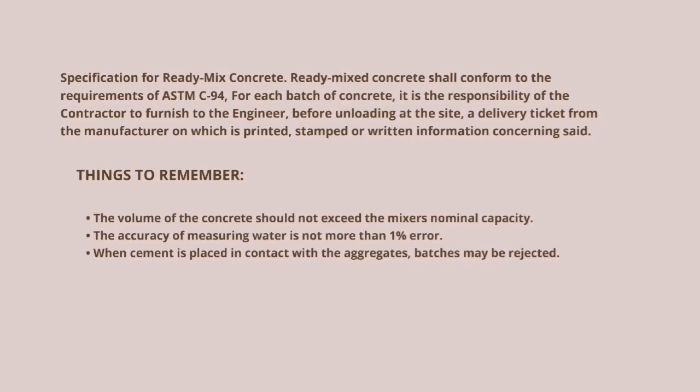Things to remember. First, the volume of the concrete should not exceed the mixer nominal capacity. Second, the accuracy of measuring water is not more than 1% error. Third, when cement is placed in contact with the aggregates, batches may be rejected.